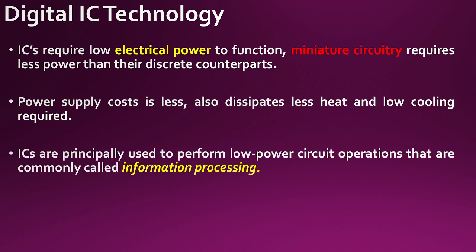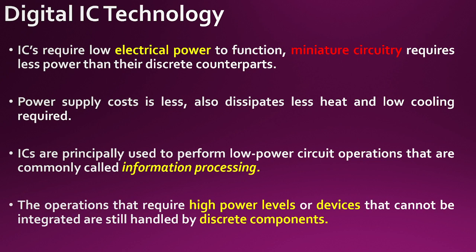If we talk about integrated circuits, these are low power circuits, and the operations are commonly called information processing. Operations that require high power levels, like high power switching circuits, are different. Even certain sections in the regulated power supplies, the switch mode power supplies, and other types of power supplies still require discrete components, because they take a lot of power.